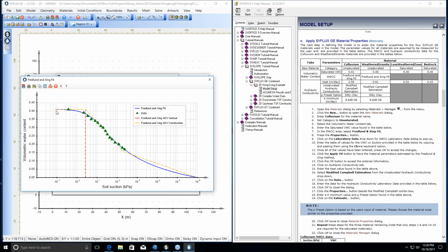So what's happening in the soil here is it's saturated out here, and then what we're applying in the soil is increased tension in the water phase, or suction. As we're applying that, at first there's less change. Then all of a sudden we hit past the air entry value, and the change rate becomes more rapid, up to a maximum up around here.